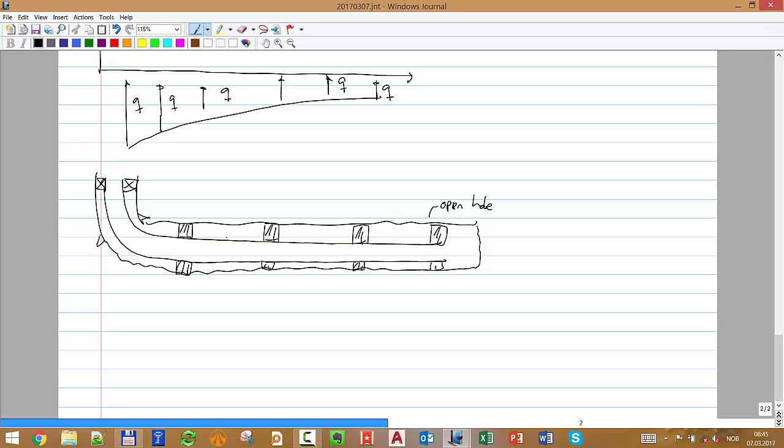And what I do next, now I have to communicate, right? If the fluid wants to come from the formation and inside the tubing, I have to make a hole. But then what I do, I say, if I expect here the drawdown, now I have PR and PWF, that difference is the biggest at the heel. And here, PR, PWF, that will be the smallest. So I'm going to make a very small hole at the heel, and a big hole here.